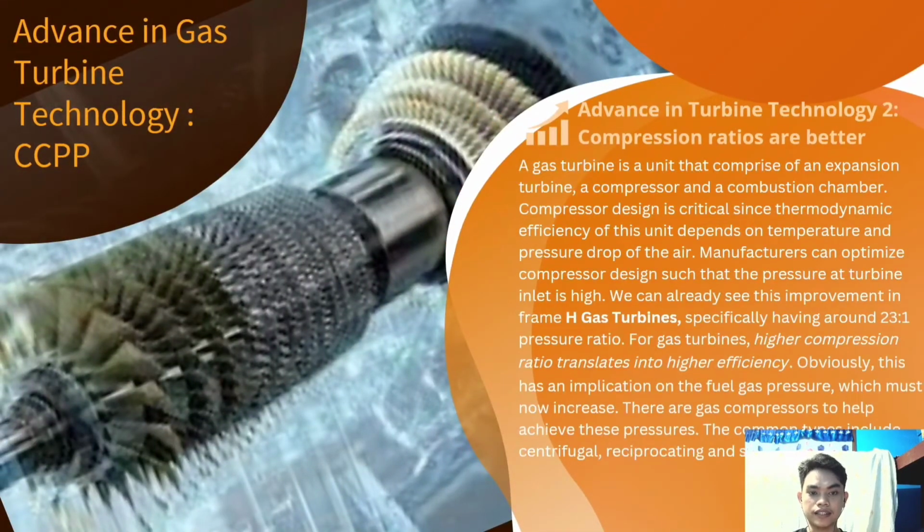A gas turbine is a unit that comprises an expansion turbine, a compressor, and a combustion chamber. Compressor design is critical since the thermodynamic efficiency of this unit depends on the temperature and pressure drop of the air. Manufacturers can optimize compressor design such that the pressure at turbine inlet is high. We can already see this improvement in frame H gas turbines, specifically having around a 23:1 pressure ratio. For gas turbines, a higher compression ratio translates into higher efficiency.